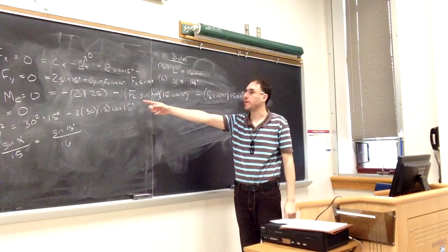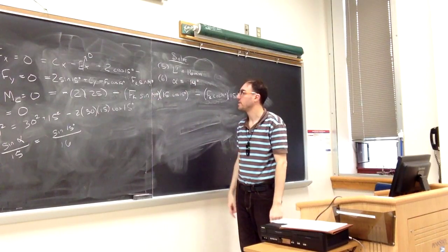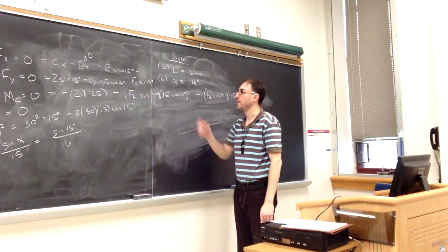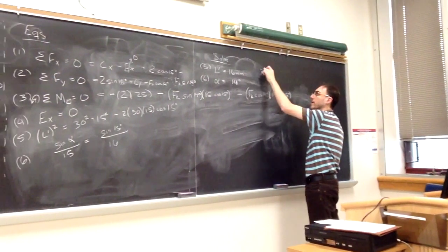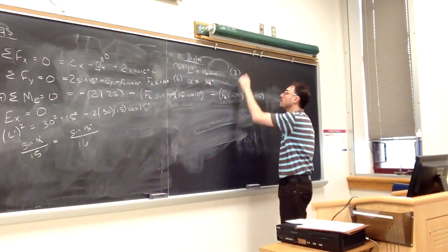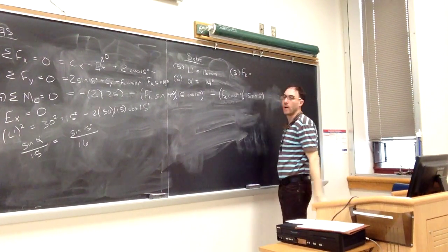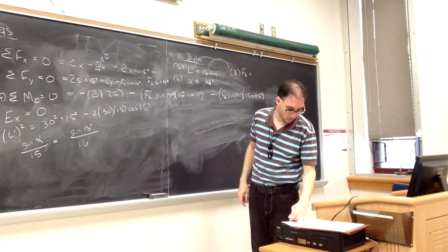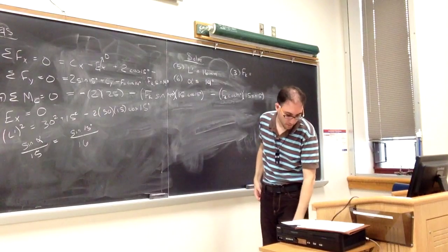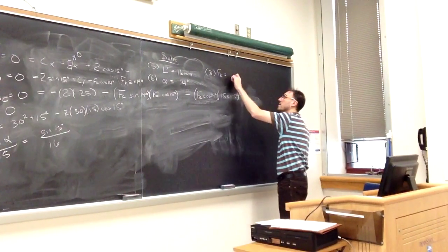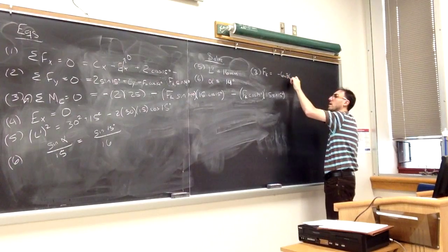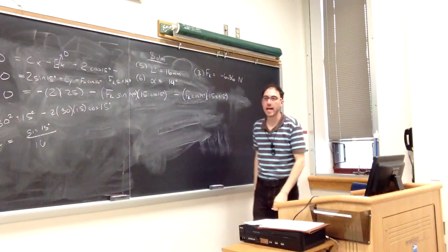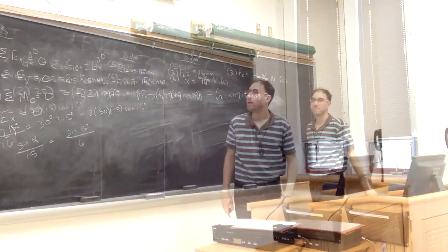Looking at my equation 3 though, the good part here is I have only one unknown because I took the sum of moments around C. So the one unknown is Fk, which I can solve immediately using equation 3. So the force in the spring, when it's just on the verge of switching, I find that that force is 6.86 newtons. And it's negative, it's actually in compression.